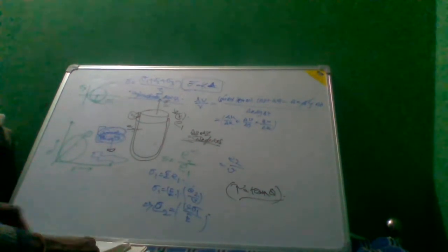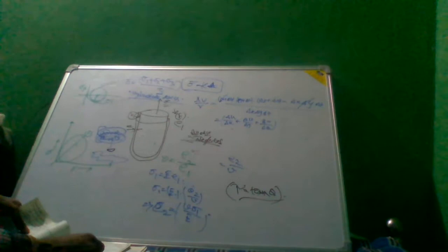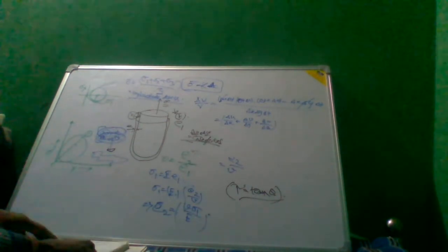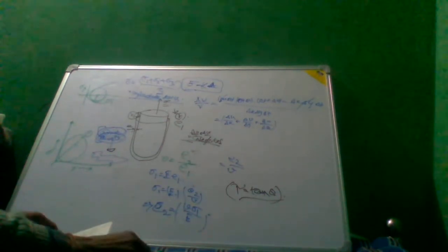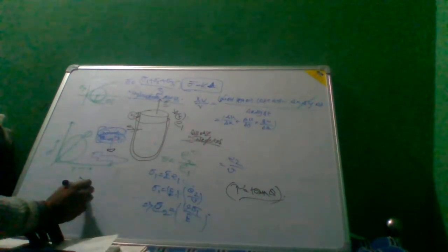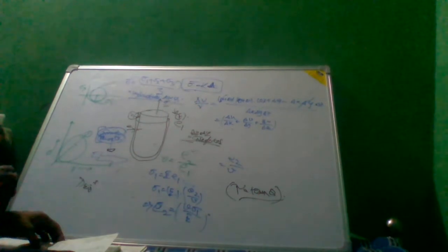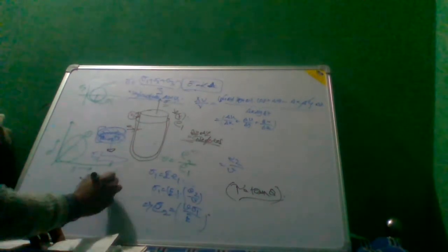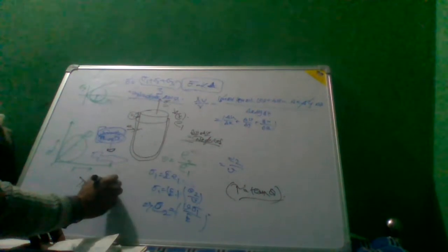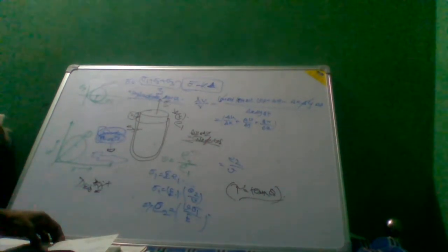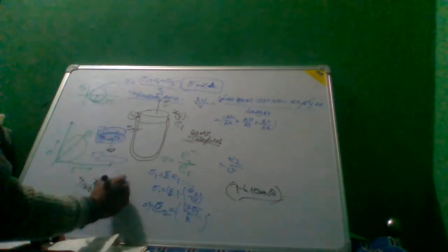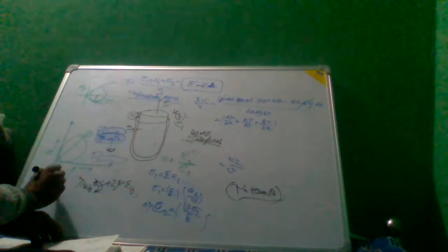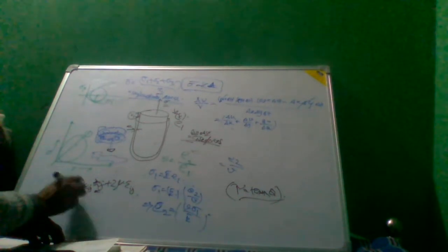From the equation that we are going to use, where we have shown that the Lame's parameter is lambda of epsilon kk into delta ij, the Kronecker delta, where when i and j are the same, delta ij will be 1, plus 2 mu into epsilon ij will be sigma ij.